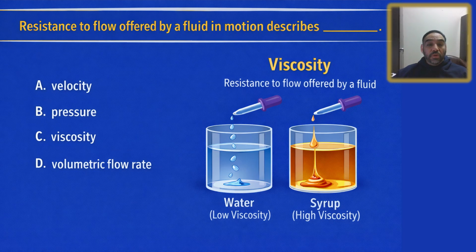Now, I was talking about answer B, pressure, right? So pressure is what pushes blood forward through the vessels, and resistance, like viscosity, works against pressure. So in my case, my oil lamp is on, indicating that I either have low pressure or high pressure according to the sensor. Otherwise, what it's telling me is the pressure of the oil is not within the tolerances of what it should be. So it could have thickened up, maybe some of it burned off and it's just thickening up and I need to change it. Or it could also mean that I don't have a pump that's creating that pressure. That could actually mean something worse, that my oil pump is not working, creating pressure, so the sensor is not detecting the right pressure.